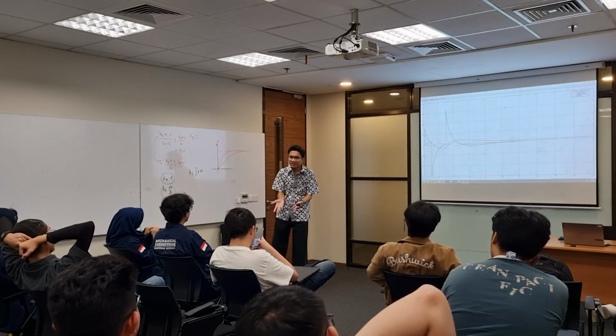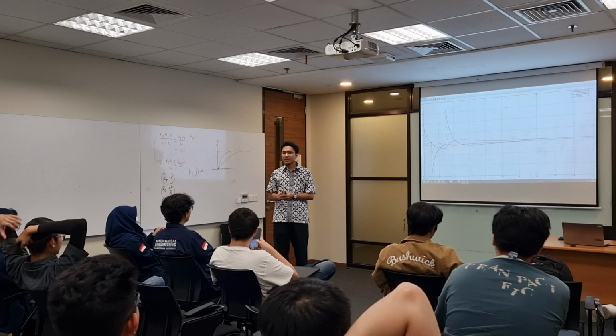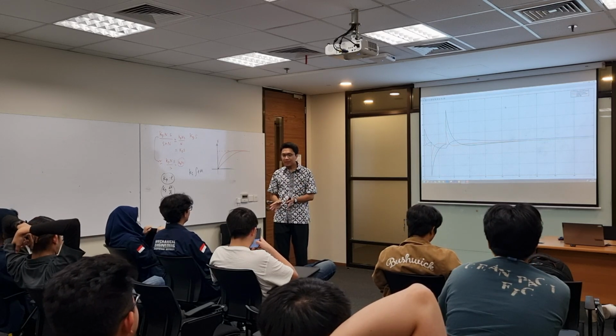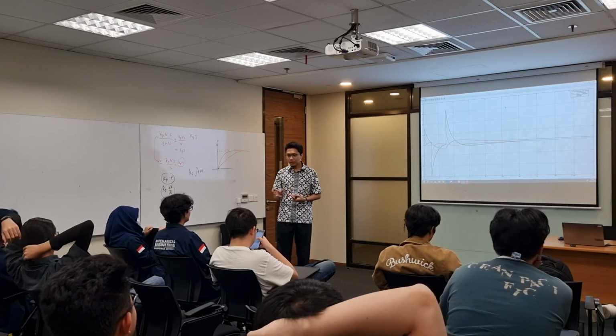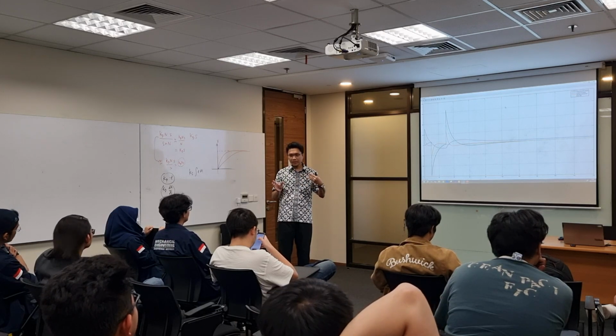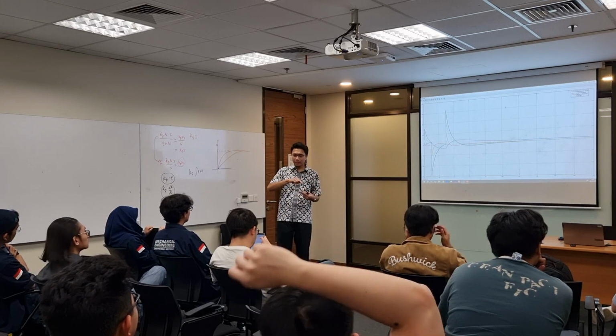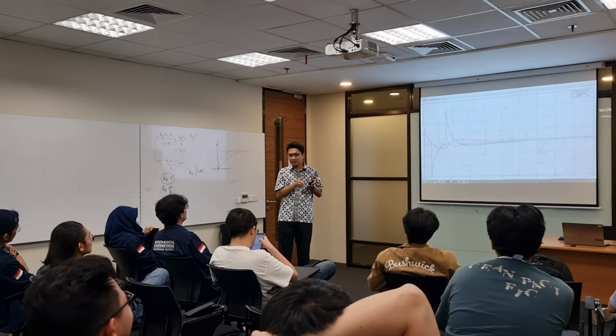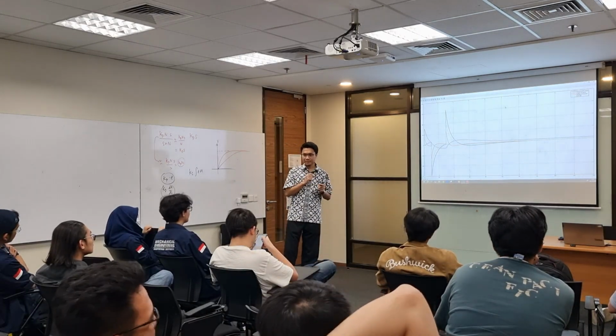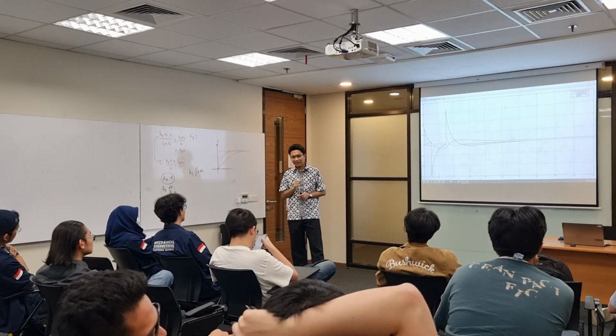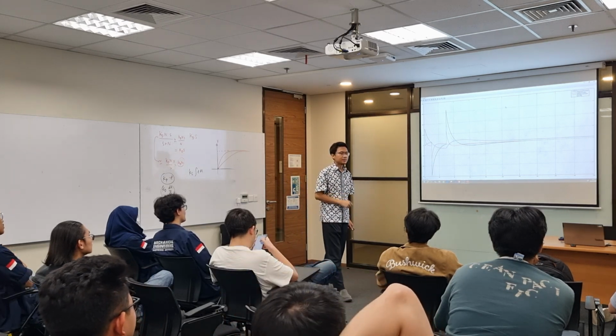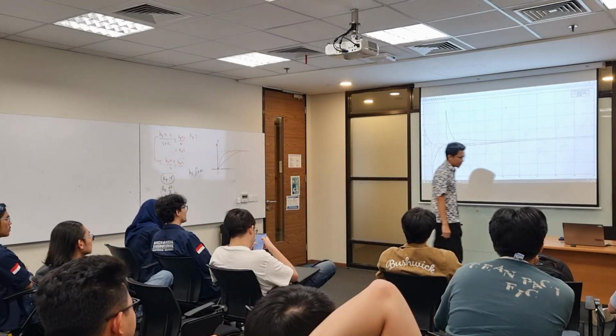That's why it depends, right? If the input is a step, then PI control can work. But if you compare with PID, then the D part will help you speed up your response in the beginning of the response. But it is optional.